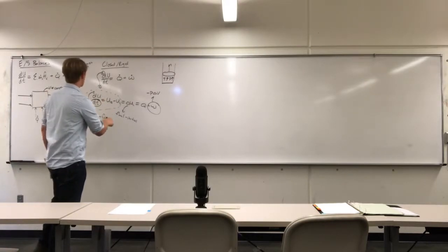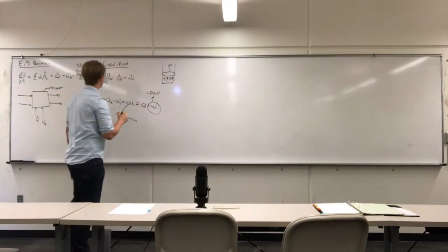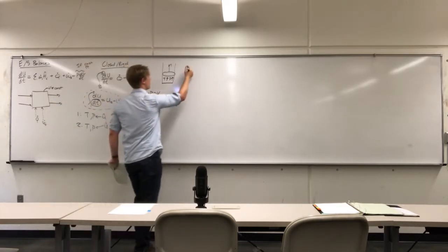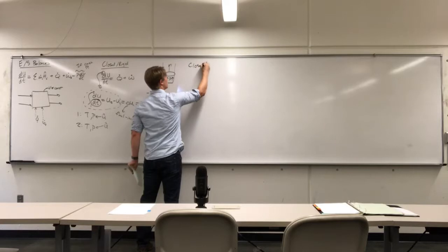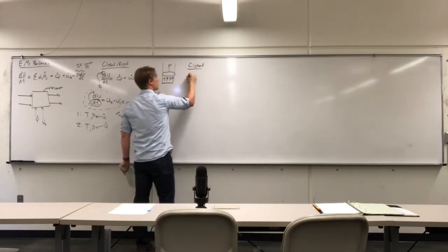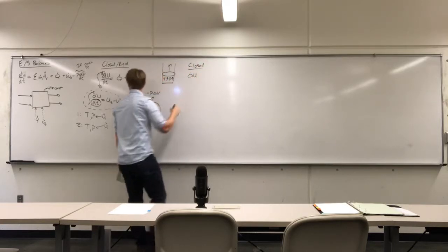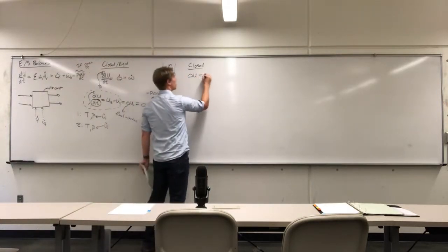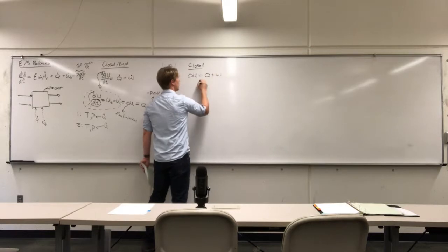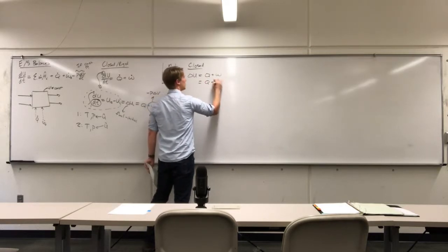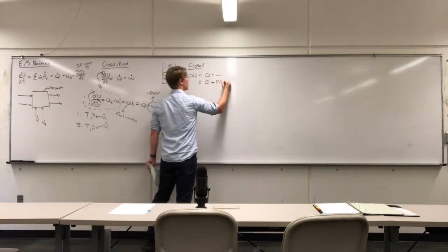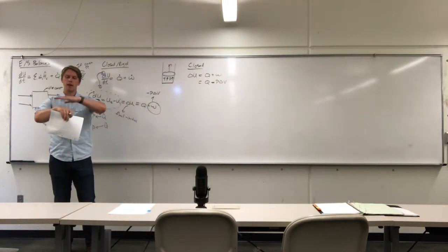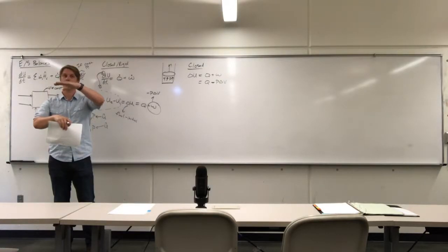One last thing that I want to talk about with the closed rigid system here. If we get rid of the rigid criteria and we say it's closed, if we look at the energy balance in an integral form, this is the differential form, the rate of change, and after we've integrated, this is the integral form. If we rewrite the work as volume expansion work, that's how much work it takes for the piston cylinder device to push back the atmosphere at pressure P.